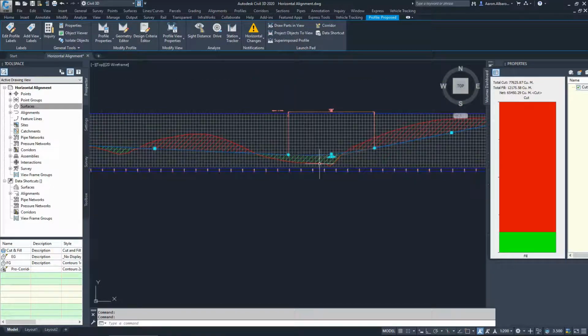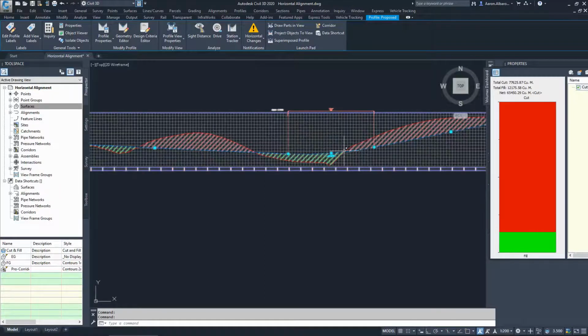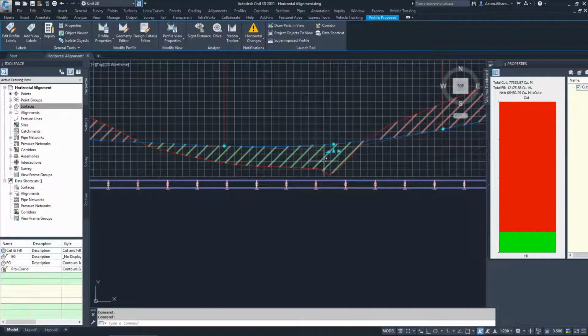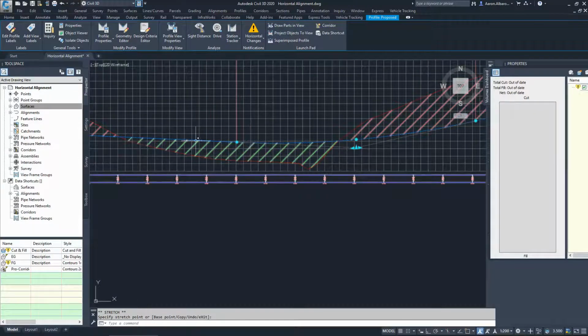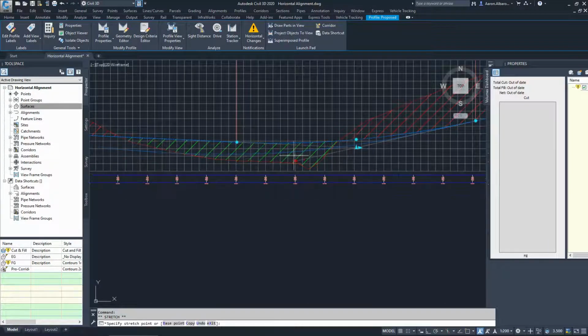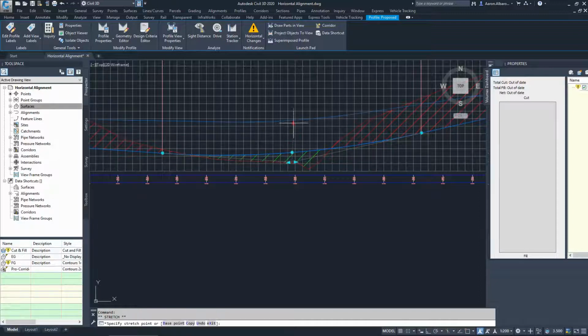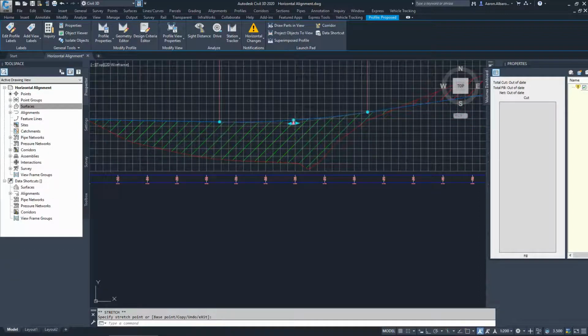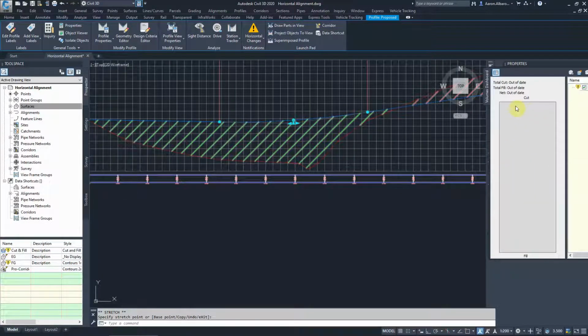One of the handy tools, first of all, obviously here we are adjusting the height of the profile for the proposed road. One of the important tools that you can use is the vertical intersection point here, and we've got 3 grips to allow us to move along the profile for the same grade here for the tangent before the profile, or in the other direction here for the tangent after the profile. We can move the intersection point up and down, and usually this tool by itself is sufficient to provide enough change with our amount of cut and fill.